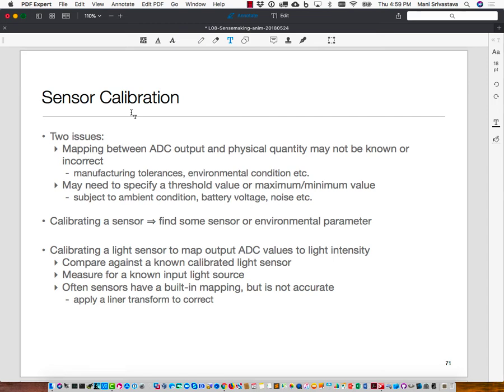And the reason for that is that magnetic sensors are very heavily influenced by exposure to strong magnetic fields or the presence of strong, large ferromagnetic structures. So that movement of 8 actually forces it to be exposed to the Earth's magnetic field in different directions and then recalibrate the magnetometer. So magnetic sensors are particularly susceptible.